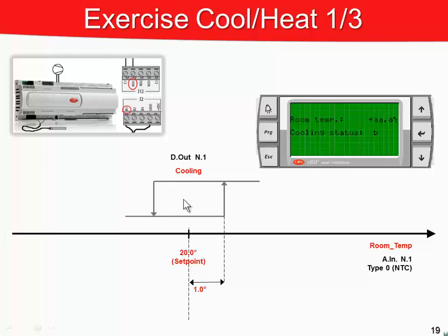It is a simple direct thermostat. I will read the room temperature from analog input number 1, that is the first that is available.